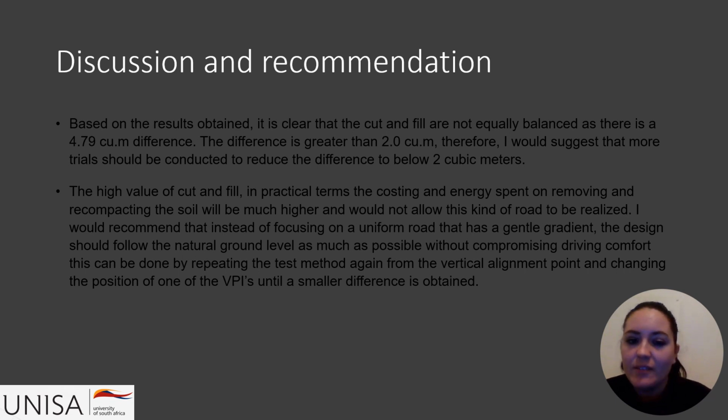The high cut and fill values were in theoretical terms correct, however in practical terms the cost and energy spent on removing and recompacting the soil would be much higher and infeasible. Therefore, instead of focusing on a gentle and uniform gradient, I should follow the natural ground level and just ensure that the slopes and the gradients in the vertical curve are still sufficient and safe.